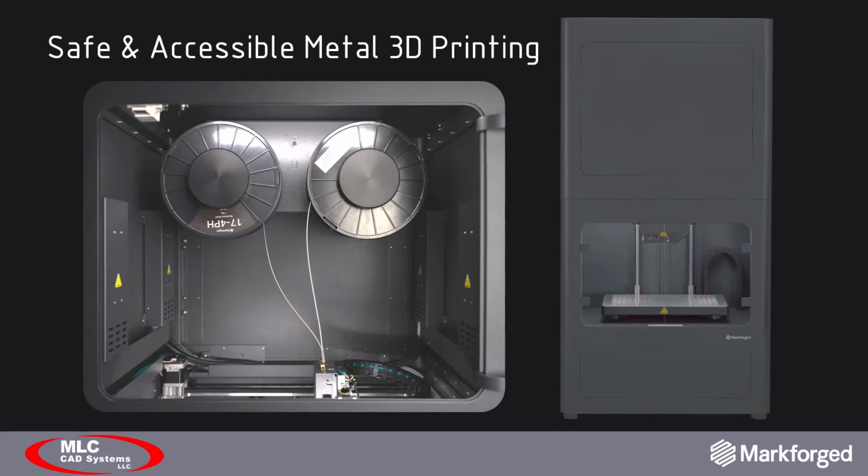You'll notice that there's actually two different spools in this image. The spool on the left is the metal material, and the spool on the right is a ceramic material that is used as an interface between supporting structures. So since this is an FDM style, we're using this ceramic support to print geometry that we might not ordinarily be able to print. We'll talk more about this here in a little bit.